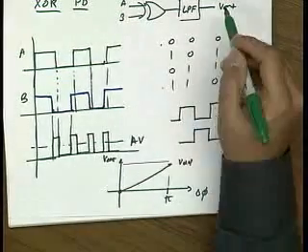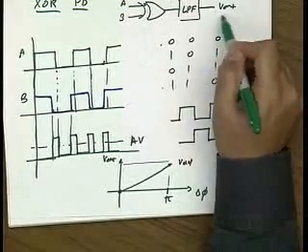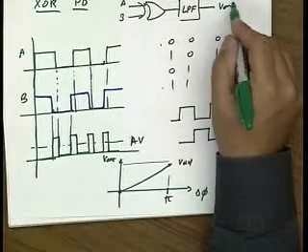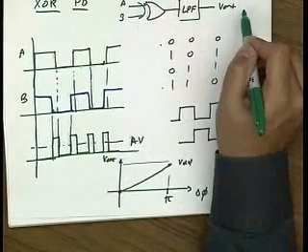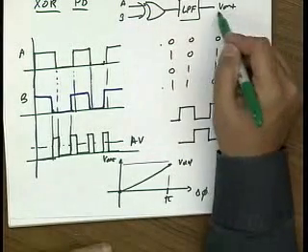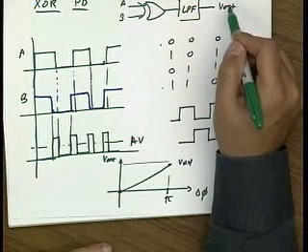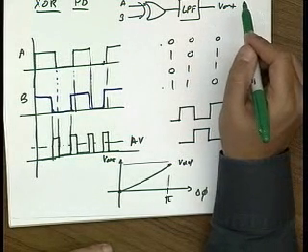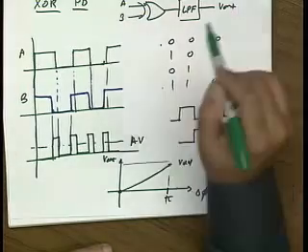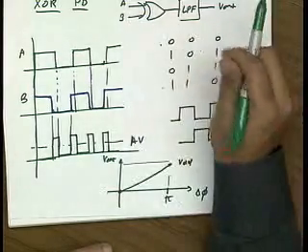Remember, what you really want here is not a constant voltage, but a voltage that tells you how far the phase shifts are off. So you can filter this, get rid of the high-frequency noise in this signal, and then apply this to the control line to pull the phase of your VCO to correspond exactly to the phase of your reference.